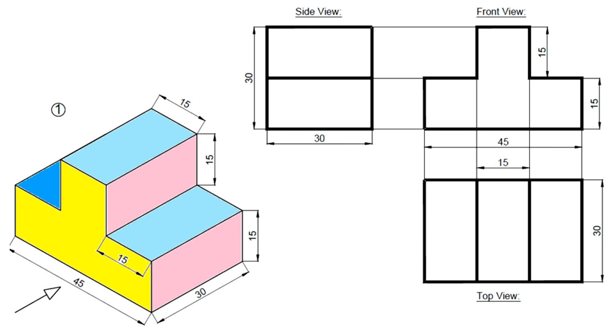If you see the object from the top side, the blue color surfaces will be visible, because these blue color surfaces are principal surfaces which are parallel to the horizontal plane. When you are seeing exactly from the top, you are able to see these three surfaces one after the other. And this red color surface will not be visible in the top view, because it is perpendicular to the ground. When it is perpendicular to the ground, and you are seeing the principal planes, this plane will not be visible and it will appear like a line.